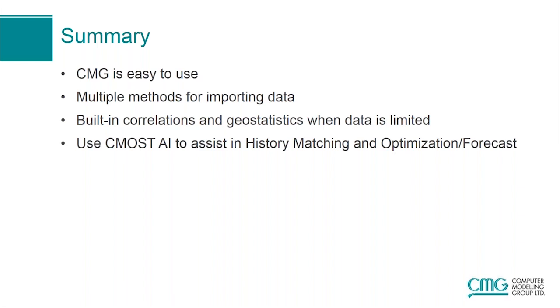But if the transmissibility or conductivity of the fault changes with time because of pressure or stress changes, then there are multiple ways you can do it. You can use the full geomechanics model, where you can use one of our geomechanics modules to change the conductivity of the sealing fault or the non-sealing fault. You can also use the Barton-Bandis method as well, that is pressure or stress dependent.